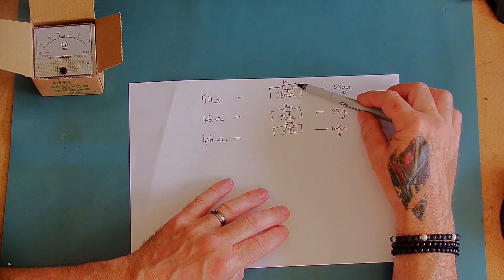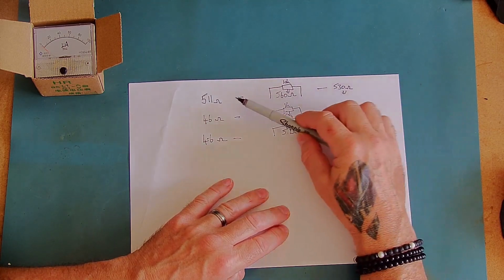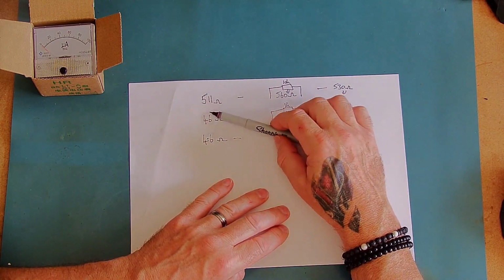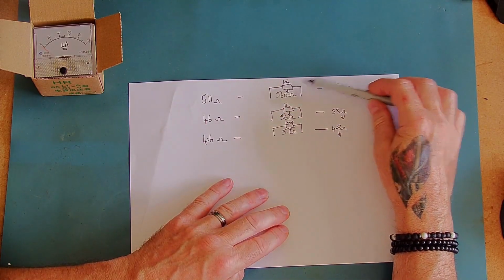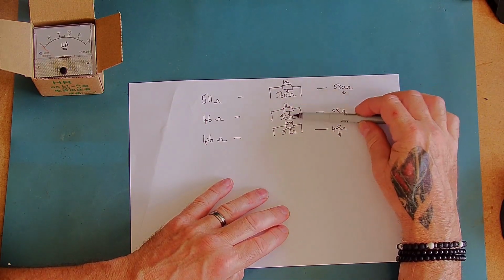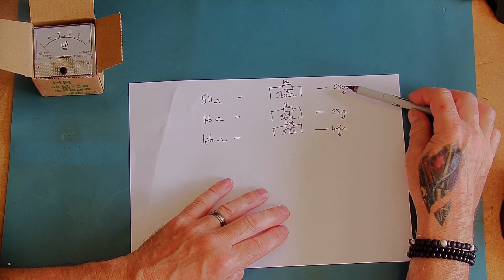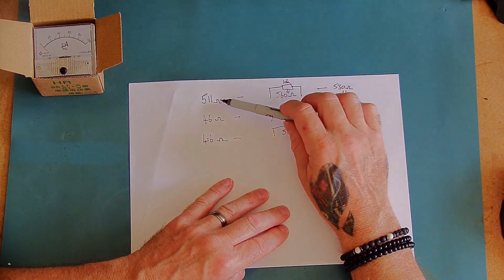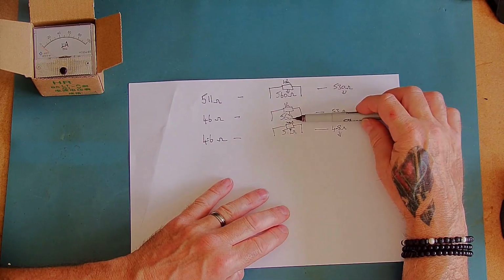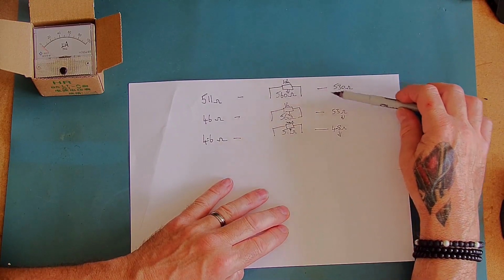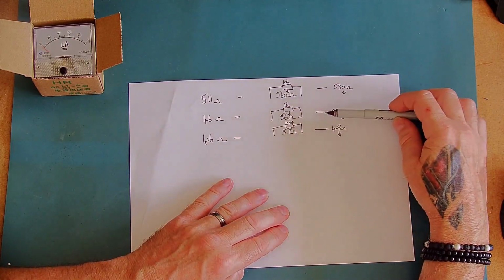So to enable calibration and adjustment, these are my nominal values. I can go from 530 ohms down, which puts 511 in range. With the 56 ohm with a 1k across it, I can start at 53 ohms and come down, that's in range.